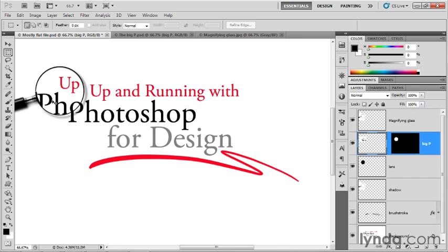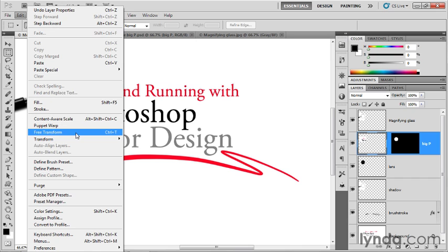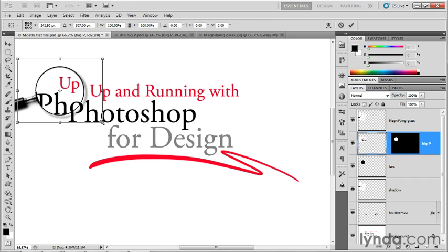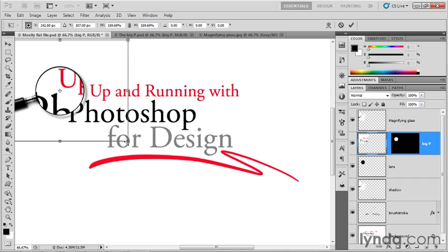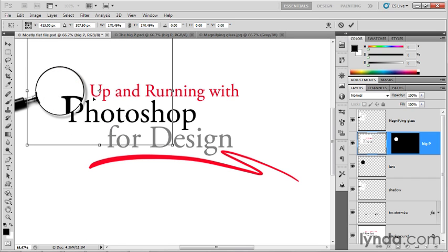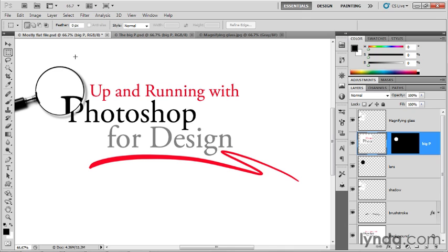And then let's go ahead and scale it and move it around. I'll go up to the Edit menu and choose Free Transform, or press Control-T, Command-T on the Mac. And I'm going to go ahead and increase the size of these letters fairly dramatically. Let's go ahead and move them over too so we can see what we're doing. And the specific percentage I'm looking for, incidentally, is 172%. So I might as well dial that in the options bar. I'll click on the chain icon to lock both the width and height values down. Then I'll change either one of them to 172 and press the Enter key a couple of times in a row in order to accept that modification.